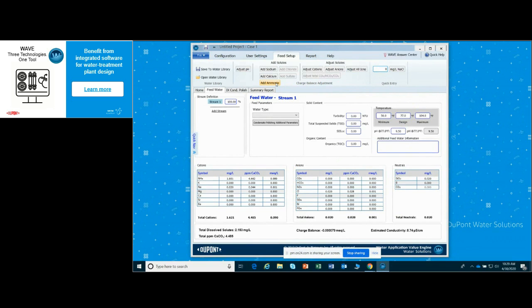Sure. Wave is actually going to use the current water chemistry, and then as it goes through the process, as you start taking ions in and out with the different processes, your charge will become unbalanced. Wave uses the charge imbalance to determine what the pH needs to be to add hydrogen or hydroxide, and also affects equilibrium like the CO2, bicarbonate, CO3 equilibria.